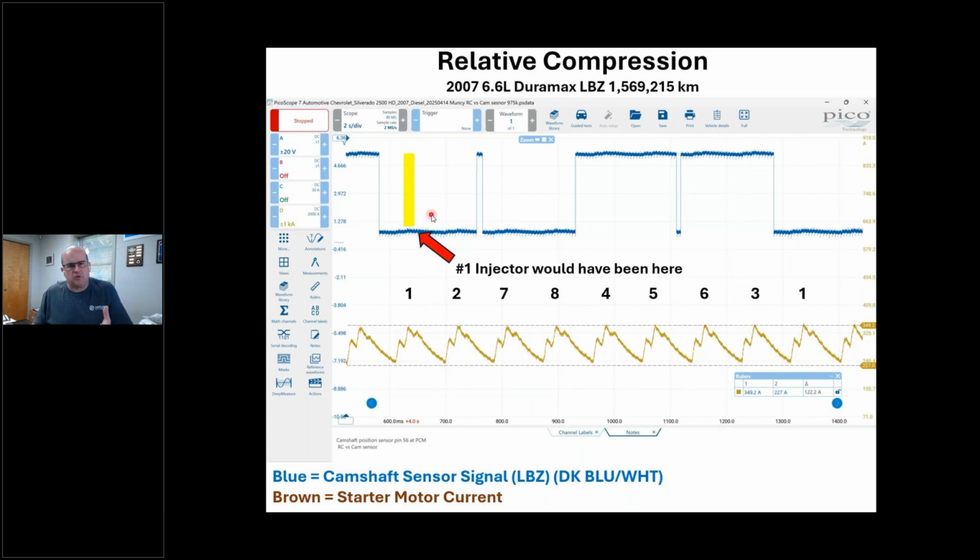Now with the crank sensor unplugged, obviously I don't have any electrical power to the injectors, because for this test I don't want the engine to start. I want the engine to crank. I want to listen to it audibly. I want to listen to the cadence, just like a band. Does it sound rhythmic? And what's my peak to peak? My peak to peak is 125-ish.